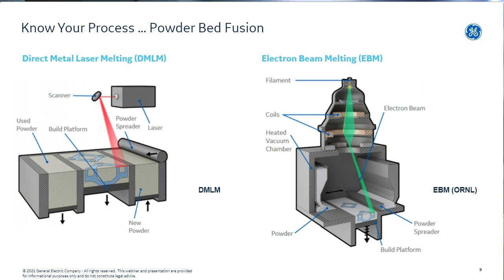The second technology here on this slide is the electron beam melting, which is from the process quite similar, but instead of using an optical system and a laser, we're utilizing here an electronic system. So you're creating an electron beam, a very high energized electron beam that then hits the surface and creates also there enough energy and power to allow to build up the structure. The risk there is on one side the electron beam itself, it's very powerful, but when it hits the surface, it generates a leakage radiation. It's more a kind of X-ray radiation, and you need to consider that when you operate this kind of machines.